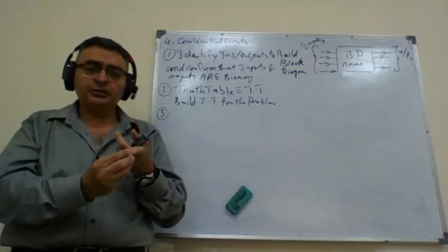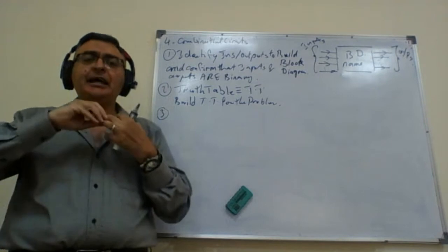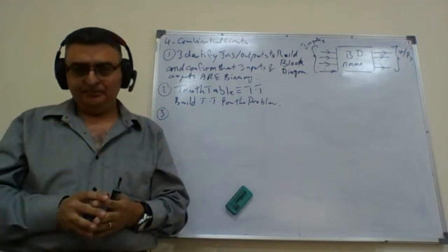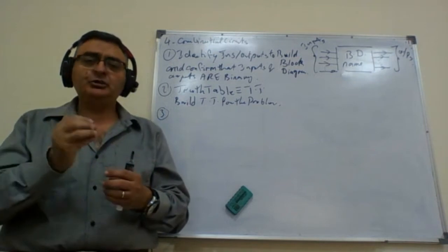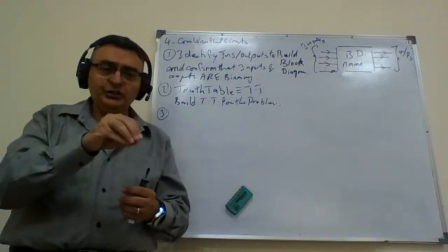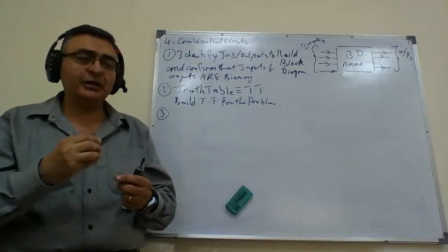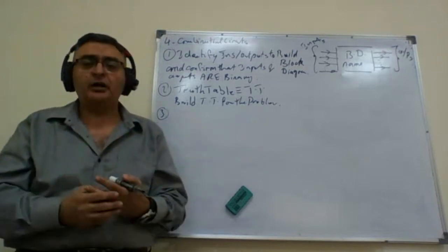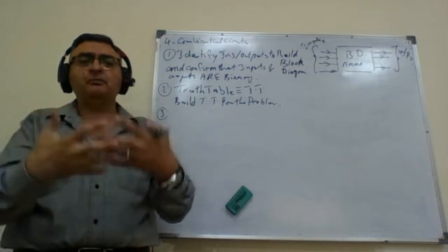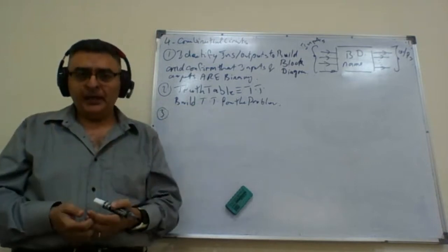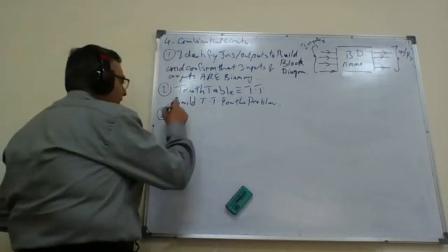One type of logic, simplified to the minimum number of gates, and has the minimum delay ever. In order to achieve those three goals, I need to simplify the equations for the problem. So I do not want to get just any equations for the problem. I want the minimum representation or the simplest equation for the problem. And this can only be achieved by K-map.